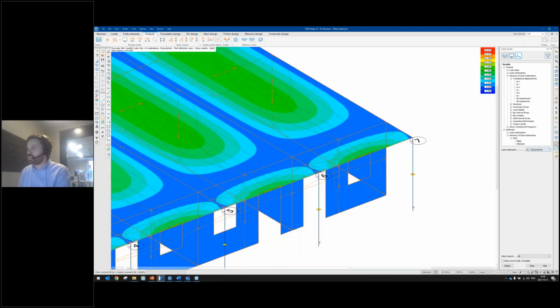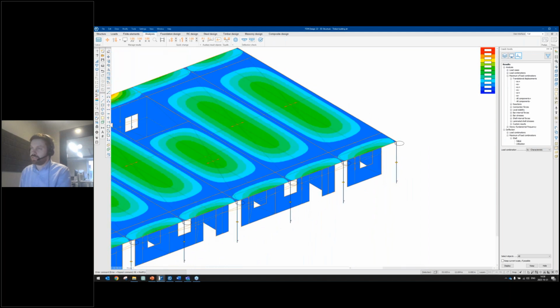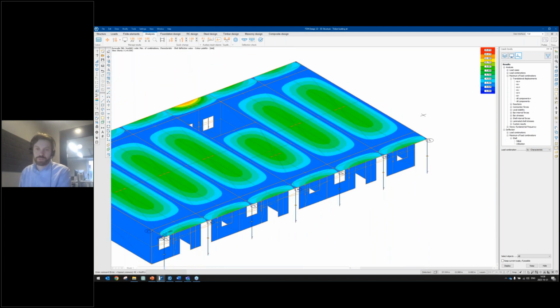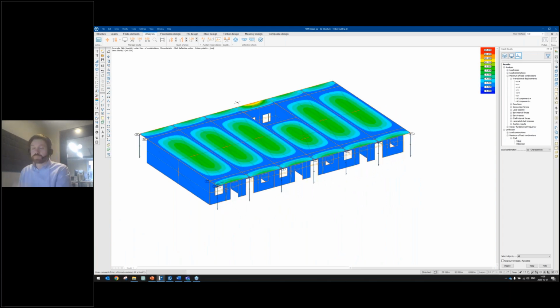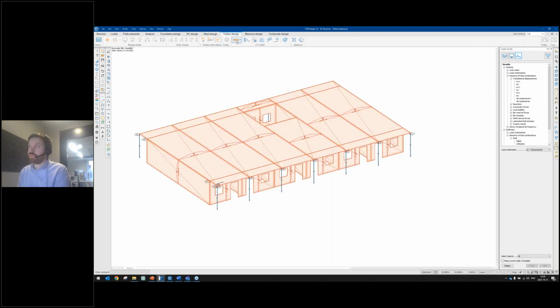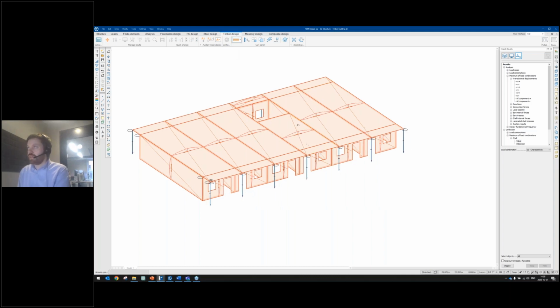So that's a neat feature, I think, to calculate the deflection checks without doing a lot of manual work or actually overestimating the deflection, because the entire structure will deflect a little bit. Let's move on to the normal ULS check. We go into the timber design, and we can select the CLT panel from the design selector here. And let's also view the entire model.